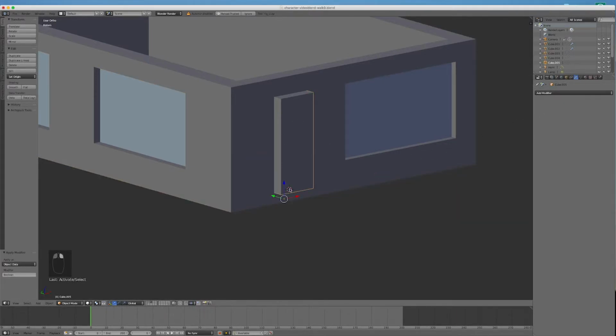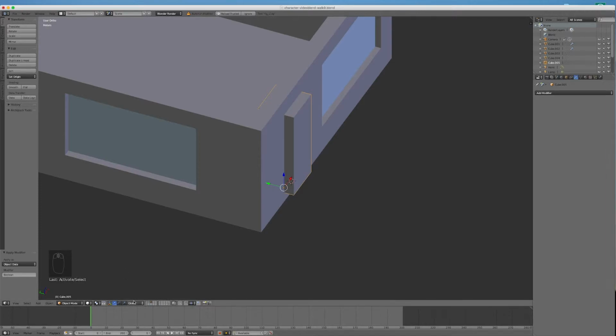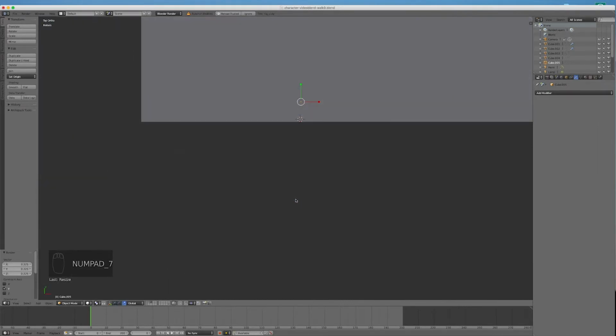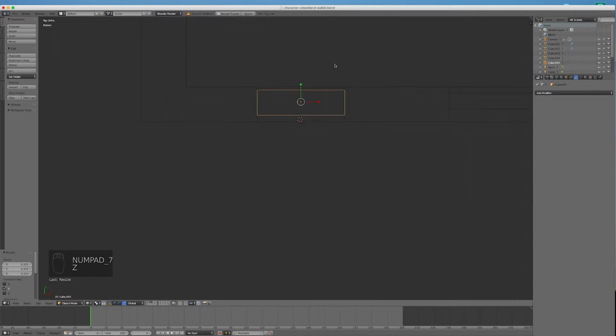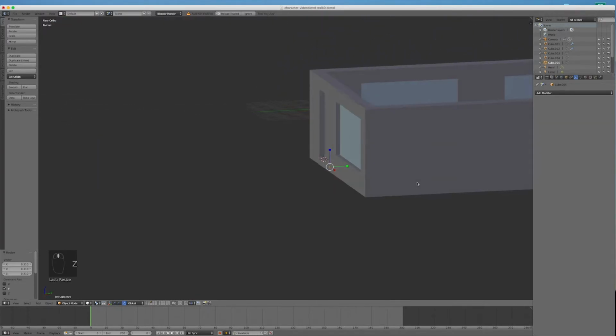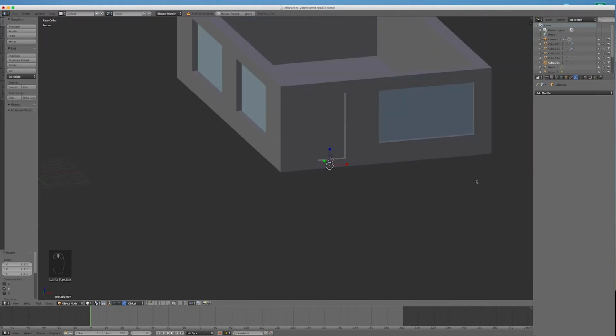We'll go to the door. We'll make this a door now. So we're using the object we cut the hole with to create the door object as well. Let's just go 7, check the width of that by going Z. Thought it was still a bit too thick. Let's make it about so thick. Okay, let's go Z and have a look. And that's looking quite okay.